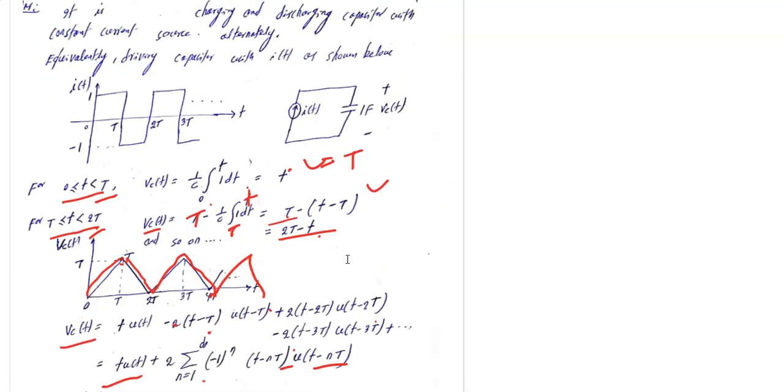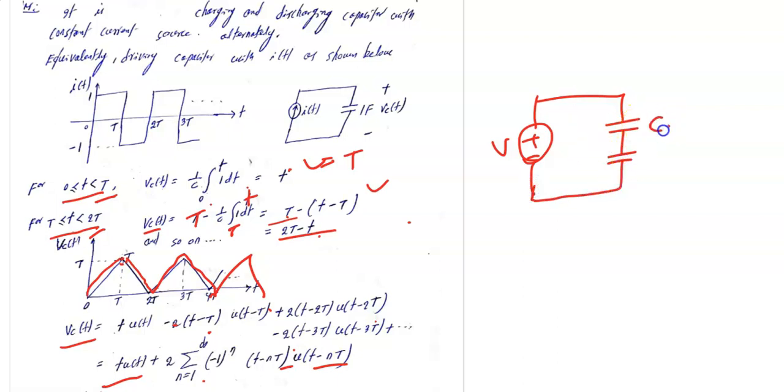So let us discuss some of the basic things. Many people are confused. So let us say we have a voltage source V and we have capacitors here, C1, C2. We need to find V1 and V2. Okay, so Q will be the same.